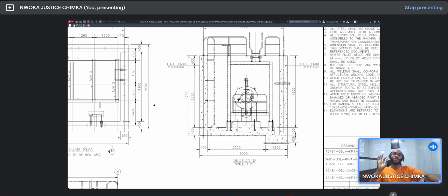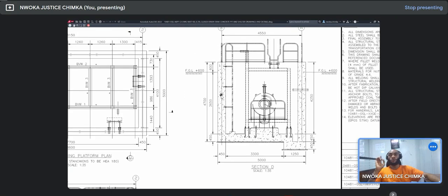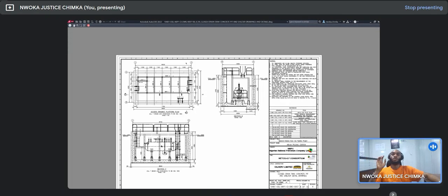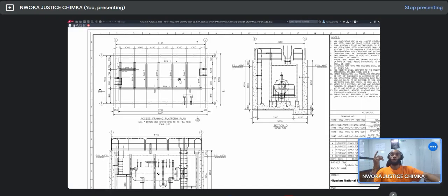Now, if this drawing is taken anywhere in the world, since I use 1:1 scale to draw it on my model space and then use 1:35 to bring it out of this place, you can see that your drawings will appear perfectly as they are meant to look. So I would advise you, whenever you're working on your drawings, always work with paper space to finish your drawings. That will be good for you to be able to achieve your perfect drawings after your printing.